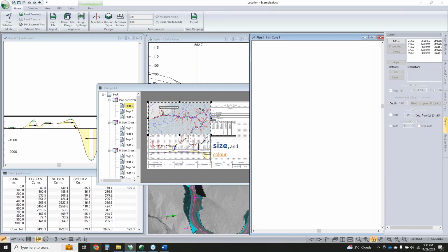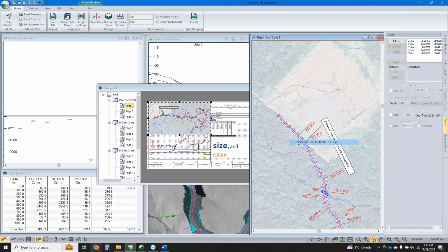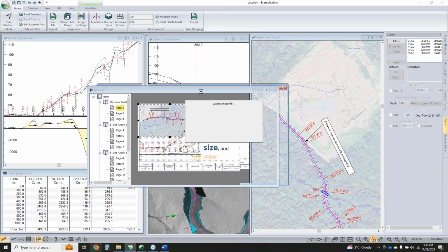We are all lined up. The nice thing about doing it this way is since my plan view has some labels that are relative to the alignment and others that are not, I don't want to set it to absolute because it's hard to see how they're going to interact with one another. So by using the orientation of that view, it makes it really easy to see where things will land and make sure it's lined up nice and straight.